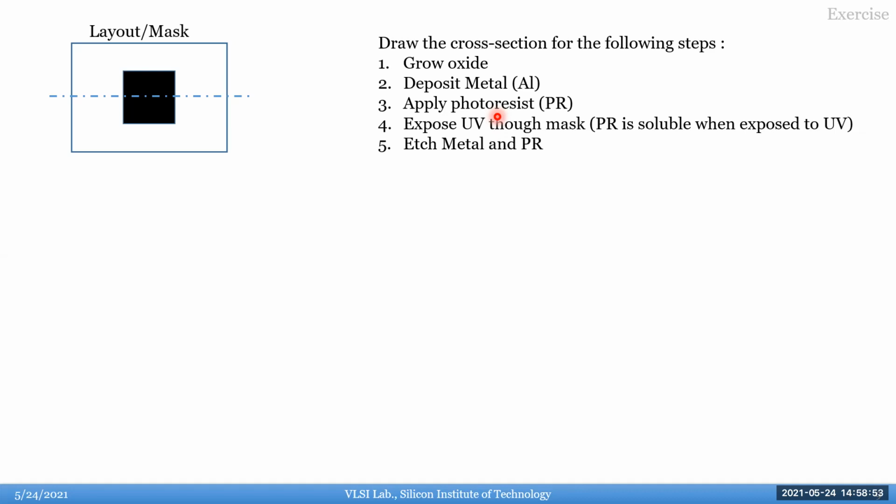Growing oxide is nothing but exposing your silicon wafer to moisture: they pass water vapor over it, the silicon oxidizes, and that oxidation just keeps growing. Okay, and that's how you form silicon dioxide, and then they take it out, polish it, and then grow the next layer and so on. So when I say grow oxide, the first step for you to do is oxide.